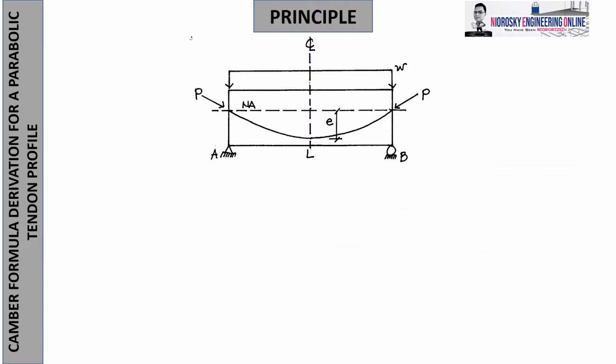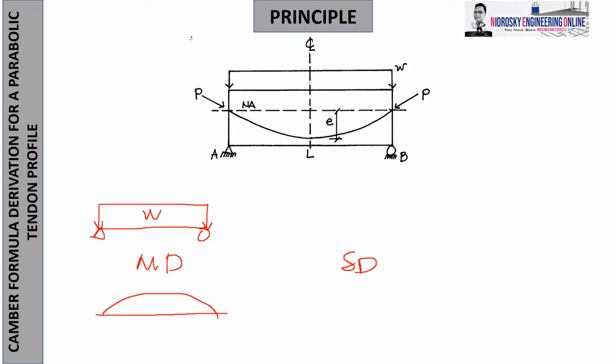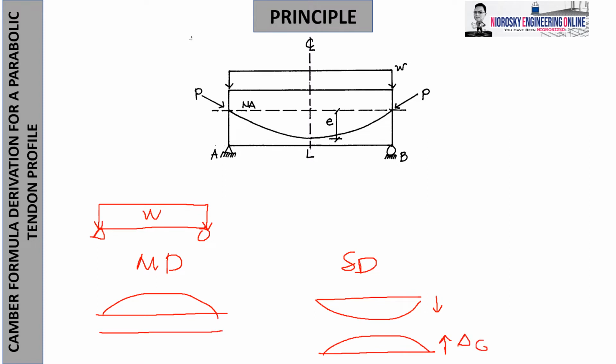Conceptualization again. So, ordinarily, from your deflection concept and moment theory, na pag may W ka, okay, ganun ulit, moment diagram and deflection diagram. So, pag moment diagram, ito yung mapoproduce natin, no? And deflection diagram is pababa. Again, we do not want a deflection that goes down. I-reverse natin. Okay, ito yung delta C. At saka that's why we will reverse the moment diagram. So, ito na ang mangyayari. Sinishade natin red ang maging tendon profiling.